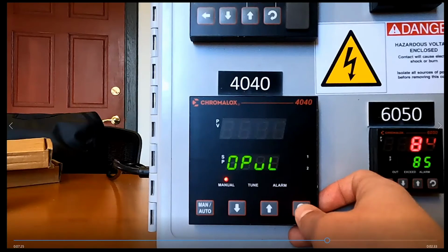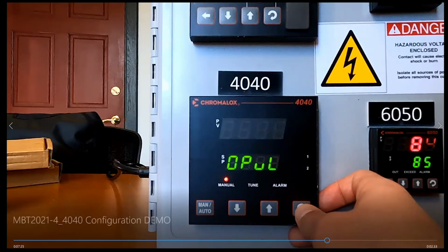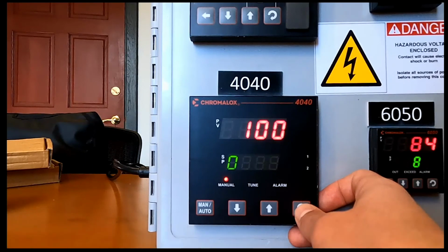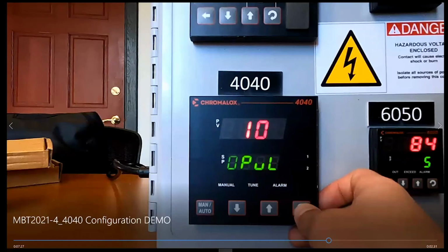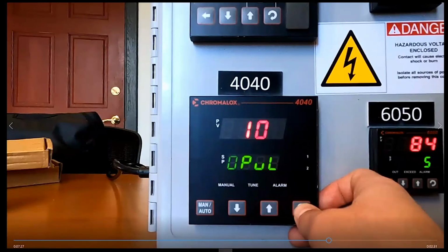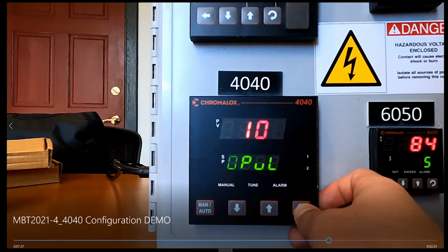Basically the default of this is 100, as in 100%. If for some reason you don't want your heater to ever give 100% power, you can dial that back. Maybe, for example, some other company sold them a heater and they totally oversized it, and so they never want the heater to get 100% power. Maybe 75% would be more than enough. You can drop this down to 75 to make sure that you never burn anything up or something like that.